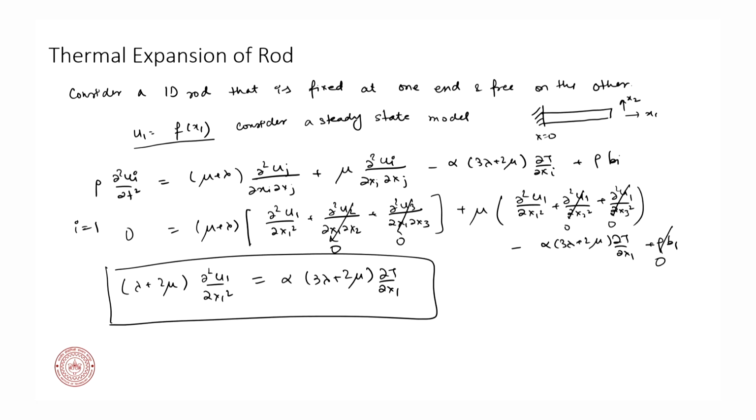We also have a thermal model. So, the thermal model we will have, likewise, rho Cp del T by del t is equal to, let us take the thermal conductivity out, K del square T by del x1 square plus del square T by del x2 square plus del square T by del x3 square plus Q dot.